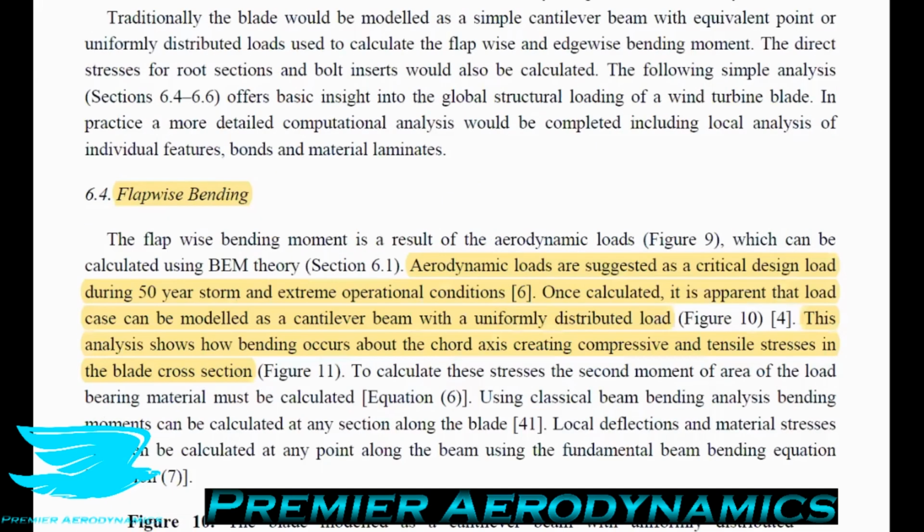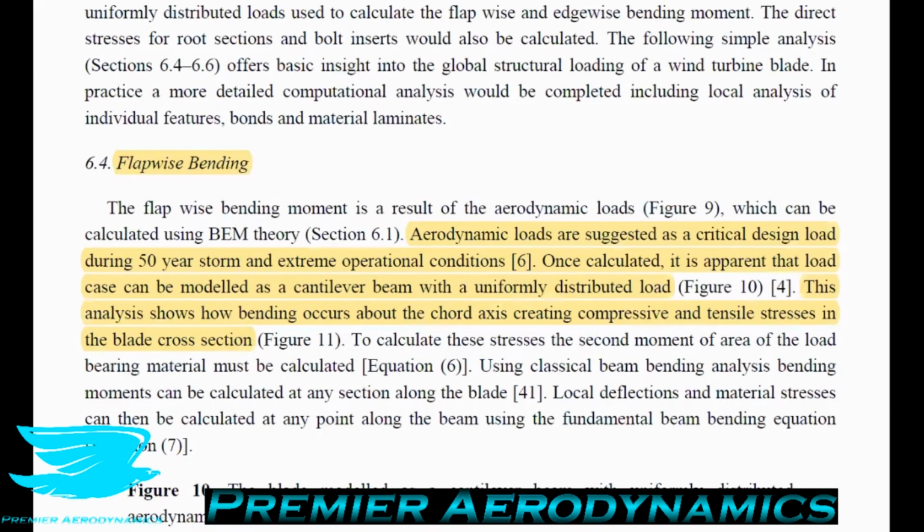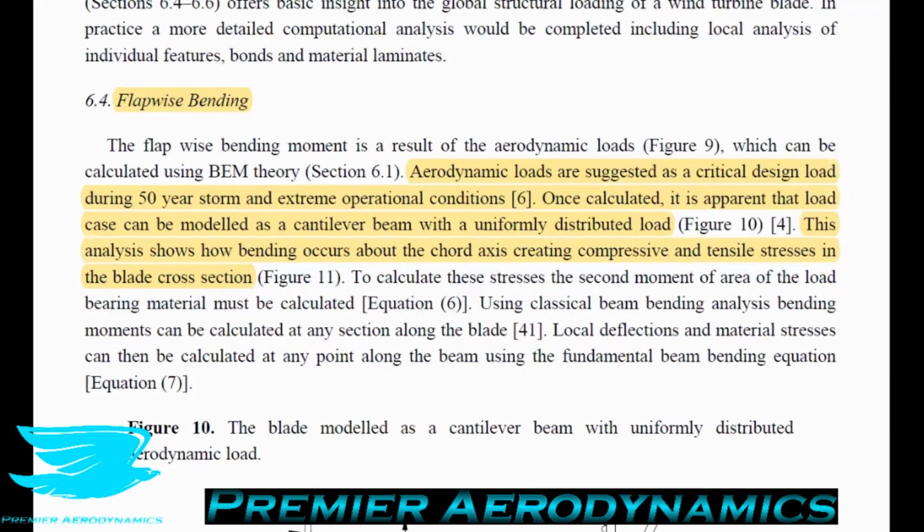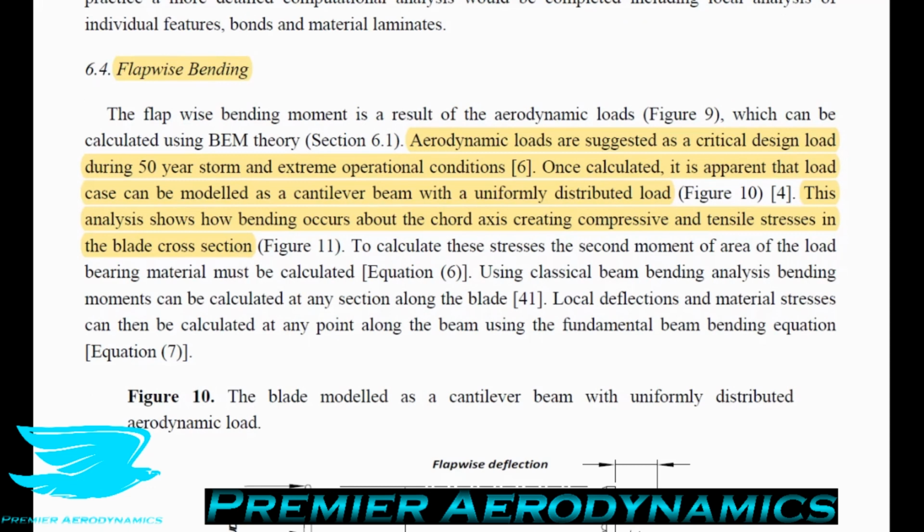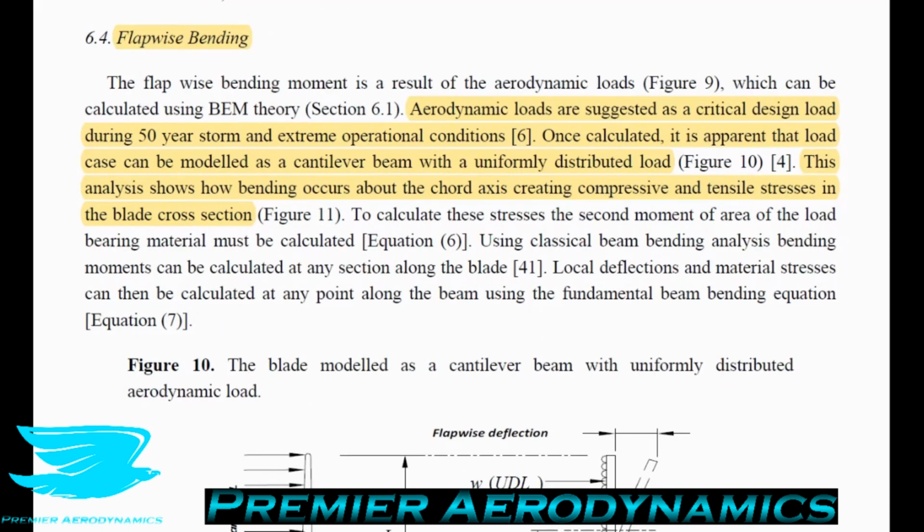Now, another interesting loading is flapwise bending. So aerodynamic loads are suggested as a critical design load during a 50-year storm and extreme operating conditions. Once calculated, it is apparent that the load case can be modeled as a cantilever beam with a uniformly distributed load. This is really important because this simplifies the loading calculations. What they're saying is, once you know what the general loading is on the blade, we can then just replicate this as a simple cantilever beam.